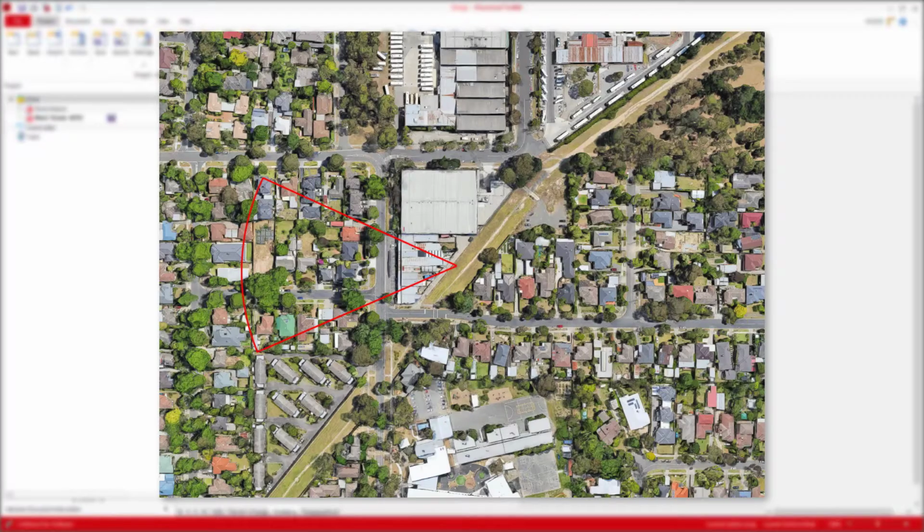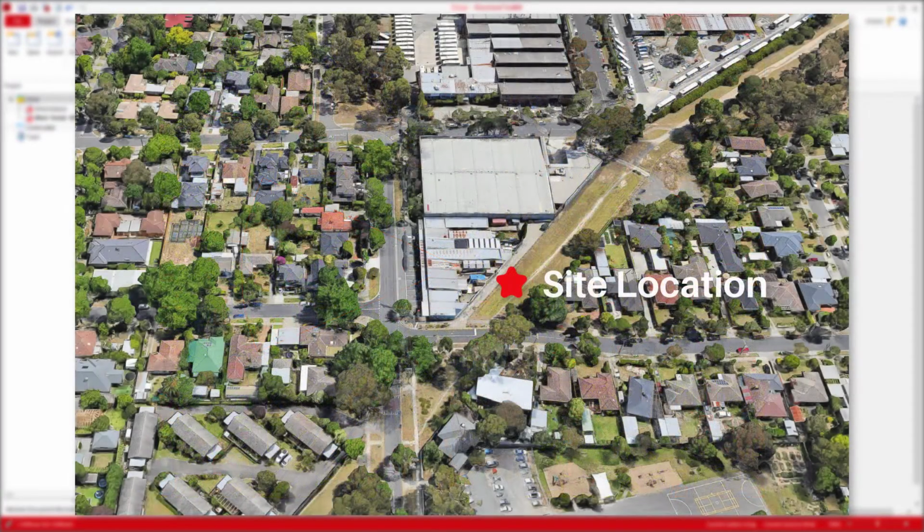If we look back on our map, this might look something like this. Having a look again at Google Maps in 3D, what we're going to be looking for is buildings that are about 8.2 meters or higher. A good place to start is in the west where our critical wind is coming from. In our case, there appear to only be a few two-storey buildings, with a couple extra here that have been recently built that we can't see on the map yet.